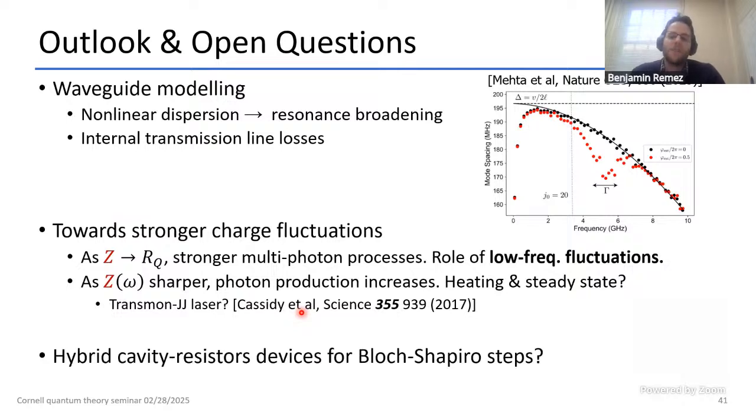And lastly, to sort of circumvent this problem I listed before, maybe you can cook up a hybrid device that has the resistance implemented both by a regular resistor and these transmission lines. So imagine a long transmission line matched with a resistor at its end. So if the resistor creates any heating, it's far enough from your Josephson junction so that the heating doesn't affect it. That's, again, a subject for further work.